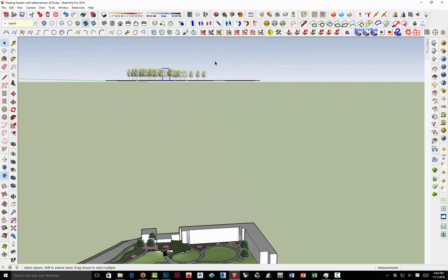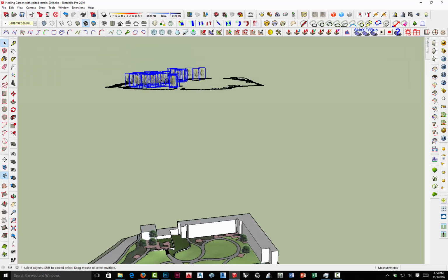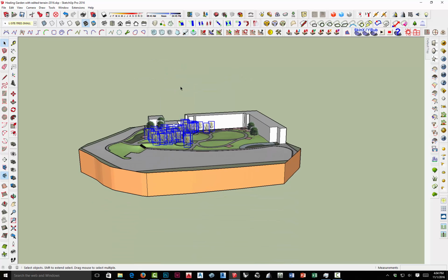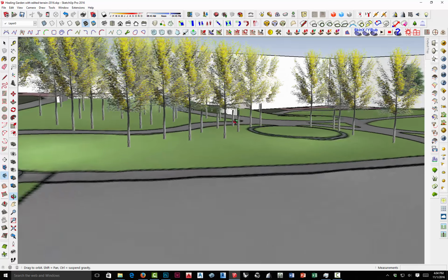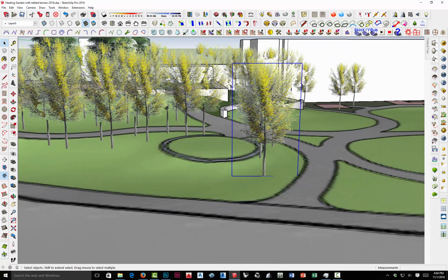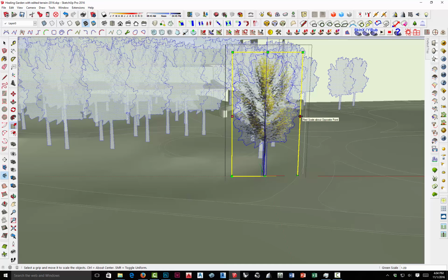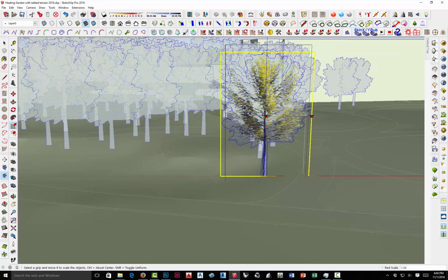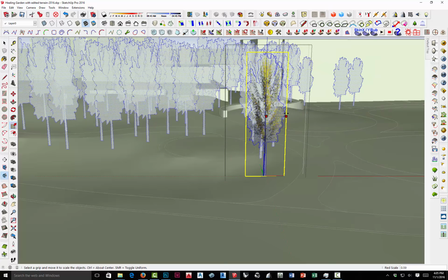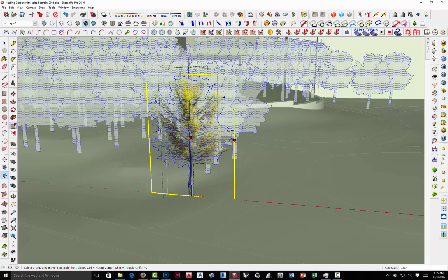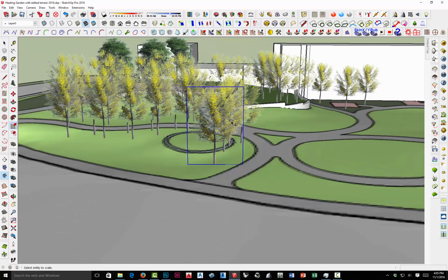I change my point of view so I can right drag across. Right click, drop GC, and there they are, all down on the surface. If you decide, again, if you want those a little bit bigger, you can open them up, double click, scale, pull it up a bit, control this. The reason I'm using the control is because, whoa, this, okay, if you see that, that's because it's snapping to something. Okay, so I change my point of view and it's not snapping anymore. There we go. You don't need to select all these components and scale them.